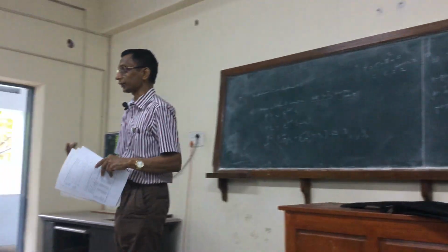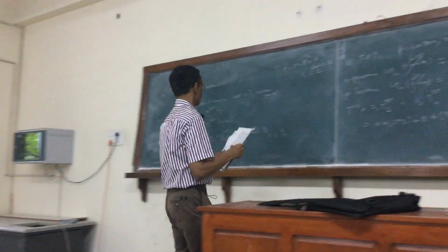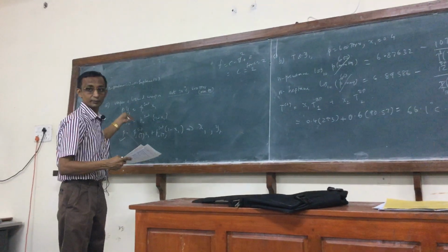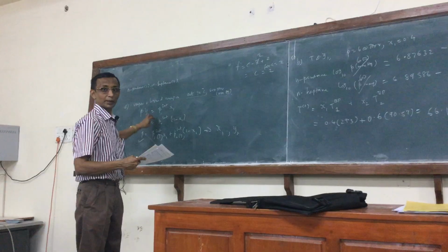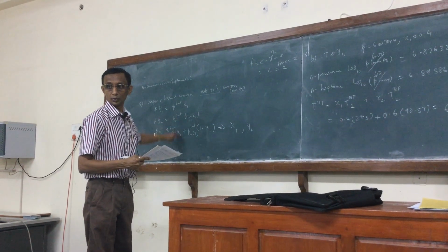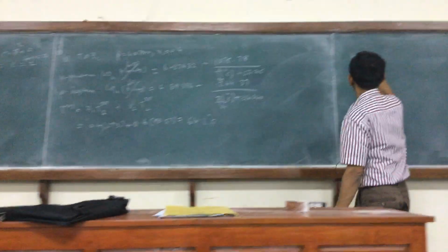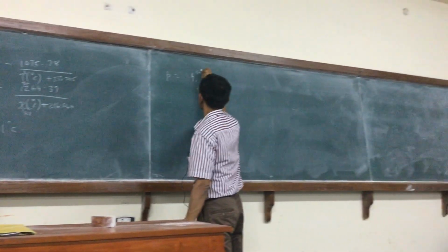So now to calculate the next one, you have to construct the algorithm. The key point here is to first apply the summation constraint on y, because that's not known. So I get P equal to P1 sat x1 plus P2 sat x2.